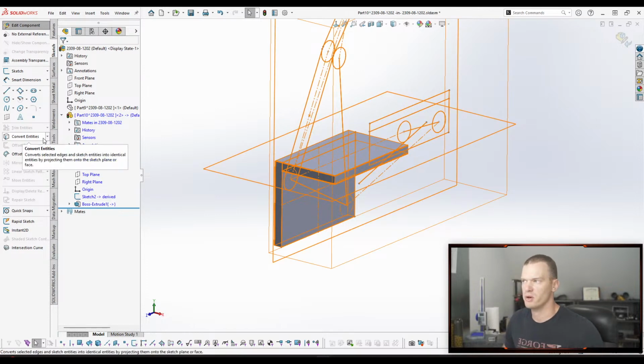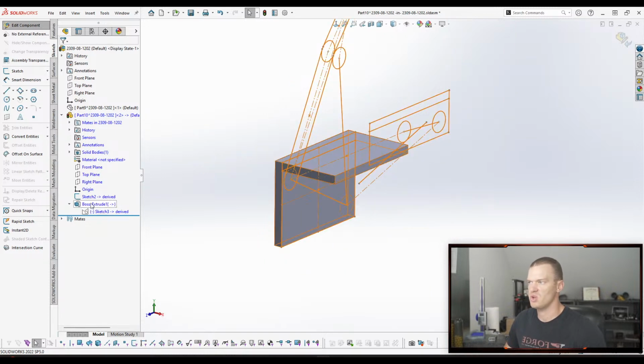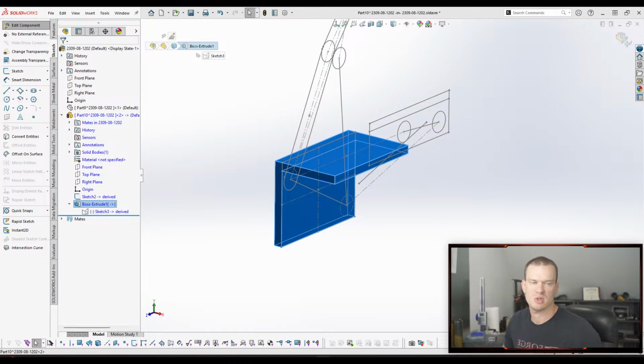We didn't convert the derived sketch entities into the sketch. You can see that this feature now hides our derived sketch. Which is fine when it's only a couple of features, but when your core sketch is hidden within your feature tree somewhere, it makes it difficult for you or the next user to come back and say, oh, there are 2 derived sketches in this part, I can see where the geometry is coming from.